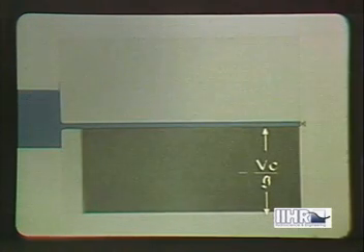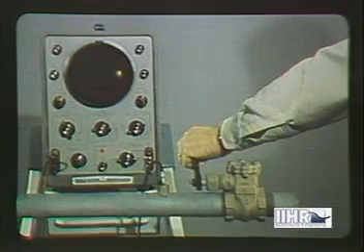As was shown in the first film, the sudden closure of a valve at the end of a long pipe causes an elastic surge to be propagated back and forth between valve and reservoir at sonic speed. At the reservoir end of the pipe, it is always reflected negatively, and at the valve end, it is always reflected positively, as a result of which the pressure fluctuates rapidly between positive and negative values, the waveform being influenced also by the elasticity and resistance of the pipe. If the initial velocity of the water is very high, the initial pressure rise can be so great as to cause rupture of the pipe.